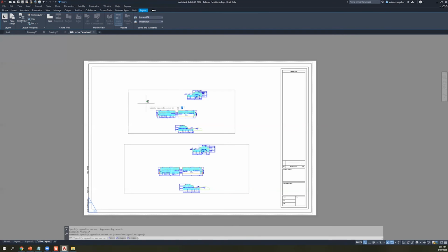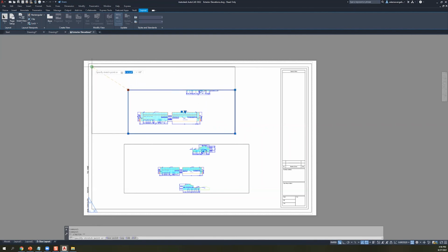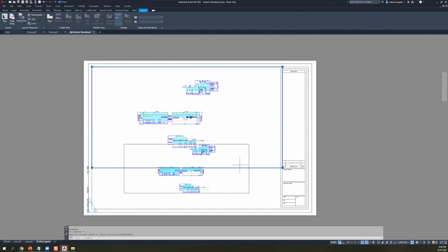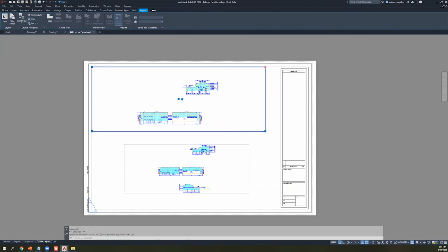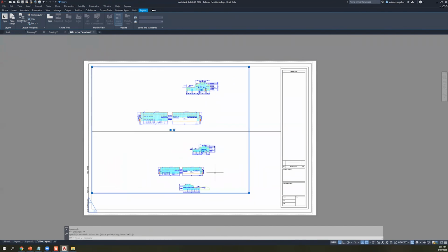Once those viewports come in, you can click on them, double click in them, zoom in there and stuff like that. But you do want to take care of the extant geometry first. And I can't emphasize this enough, but the viewports themselves and the boundaries that we're dealing with are not exact sciences whatsoever. There are obviously some snaps you could still use over here, but you don't necessarily need to worry about the dimensions of your viewports themselves. As long as you get the view that you want, you have a lot of freedom to do everything you need.